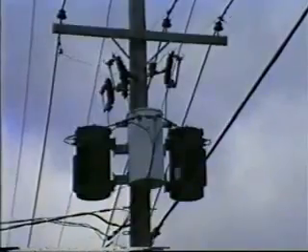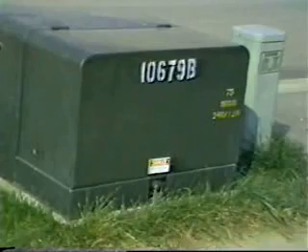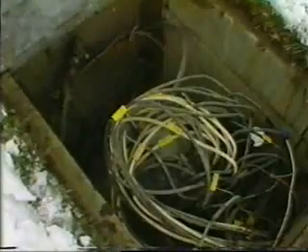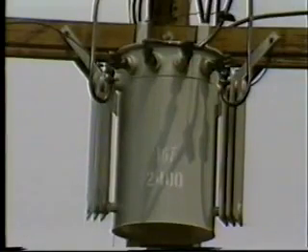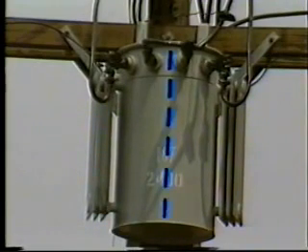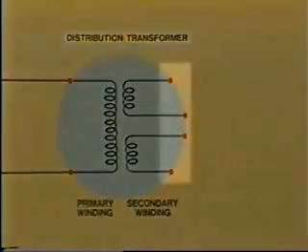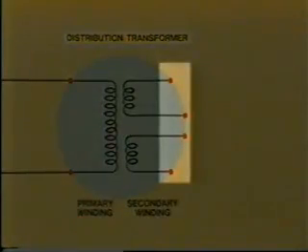In this segment, we will look at the most commonly used connections and see how they serve a variety of loads. Okay, so let's first look at some typical single-phase connections. Now, in order to provide flexibility, the secondary winding is usually split into two separate windings that may be connected in series or parallel. Interconnections can be either internal or external.